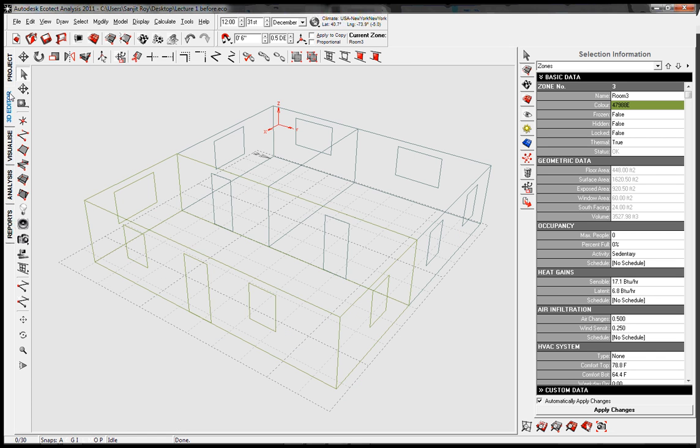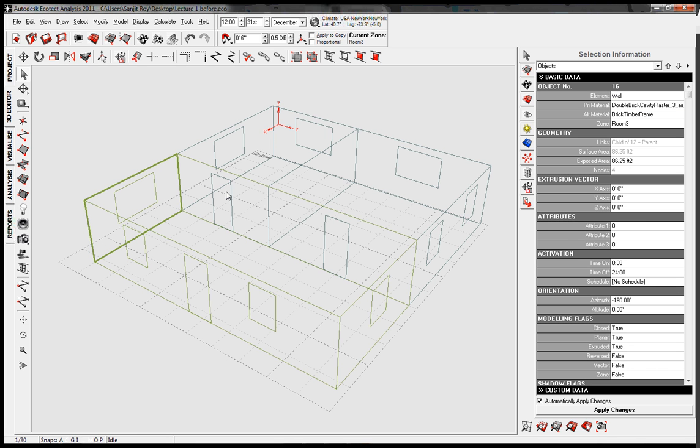Now let's click on the 3D Editor tab and see what we can do to reduce our sol air or indirect heat gain. Sol air or indirect heat gain is changed in the easiest manner by changing the color of the walls and the color of the roof. So let's go ahead and select a roof. We've been selecting the wall, you hit the space bar, it's going to toggle and select the roof. The primary material right now is being shown as a clay tiled roof. We're going to click on the arrow button and hit select matching objects, which would select all the roofs.